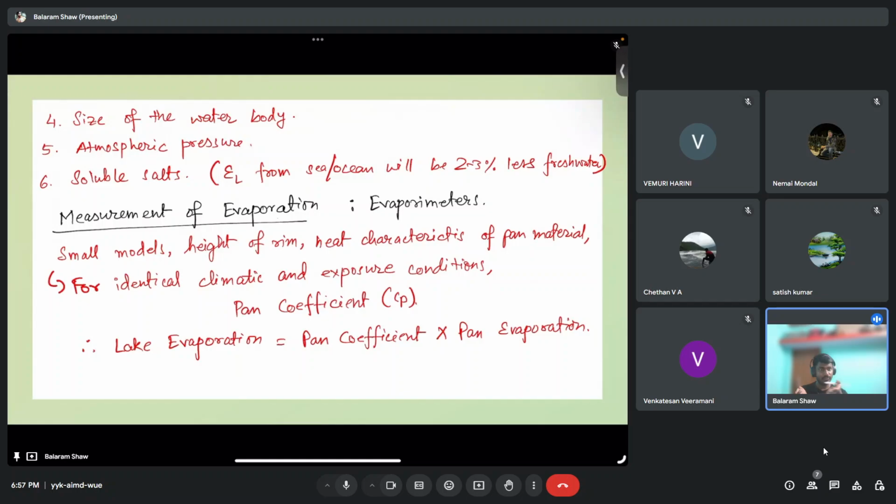Okay, so the next question is pan factor. Pan factor, as in this pan factor. It is my pencil. By pan factor I meant pan coefficient. The pan factor used in the pan evaporation method is dependent on, any answer? Anyone? The pan factor or pan coefficient will be dependent on both the season as well as the location. So the correct answer will be C.